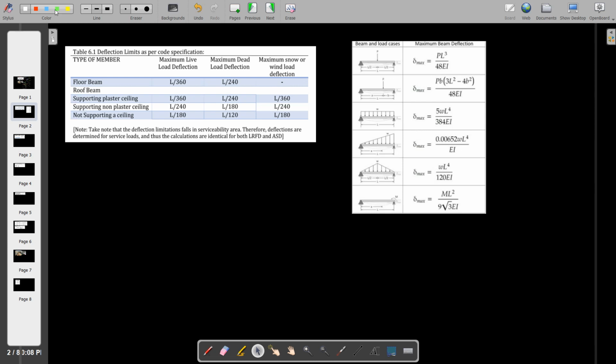So, here you just have to compare this with the calculated deflection according to the loading. Now, there are several methods to do it. But in engineering problems, we have common loadings. When we have a concentrated load located at the center, then we just have to use this formula. I think you are quite familiar with this formula. Those formulas are actually derived using several methods I'm talking about.